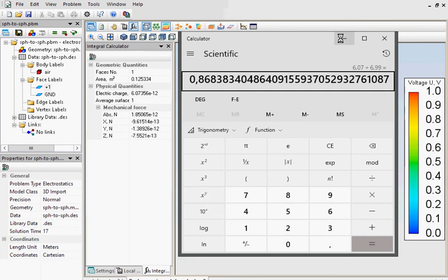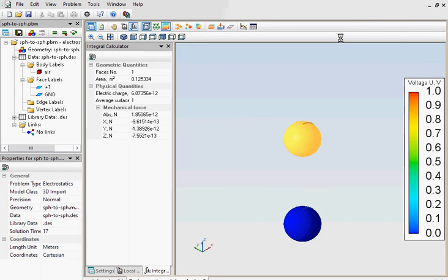If you need better accuracy, just build a denser mesh. Well, in this case we knew the analytical solution in advance, but what should we do if we do not know the analytical solution? Well, you should build the denser mesh anyway. Just in this case you will compare the intermediate results. For example, forget that we have an analytical solution. We get some results and the capacitance is 6.07 picofarads. How accurate is it? Let's build a denser mesh.